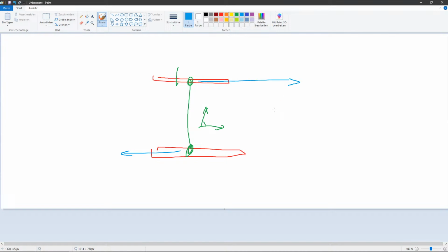And then you can maybe do something with that, like make an estimate for if the shear stress would be too high. For sure, there's nothing with bending and contact and stuff like that. That's all not being accounted for. And then, going further, if you have the force here, you could also do F divided by A for something like a pressure on the surface here.